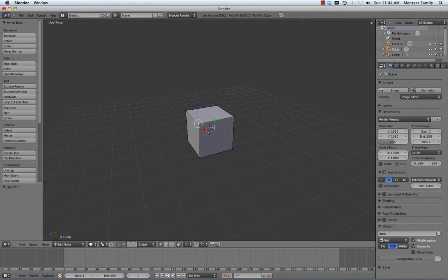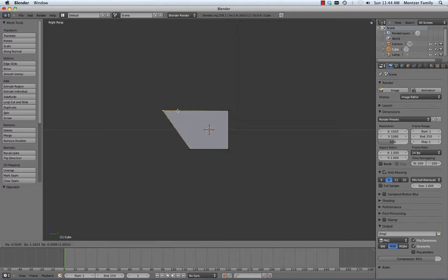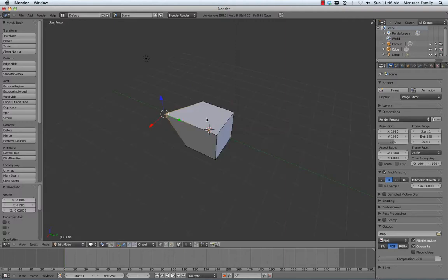It's hard to know exactly where you're moving that point unless you flip your view into front, top, side, something that works so that you can see the exact transform that you're trying to achieve. And then when you're done with that, you can toggle around to a more ortho view that's skewed so that you can see if you ended up roughly in the right area that you want and view it from a few different angles and make sure it looks right.